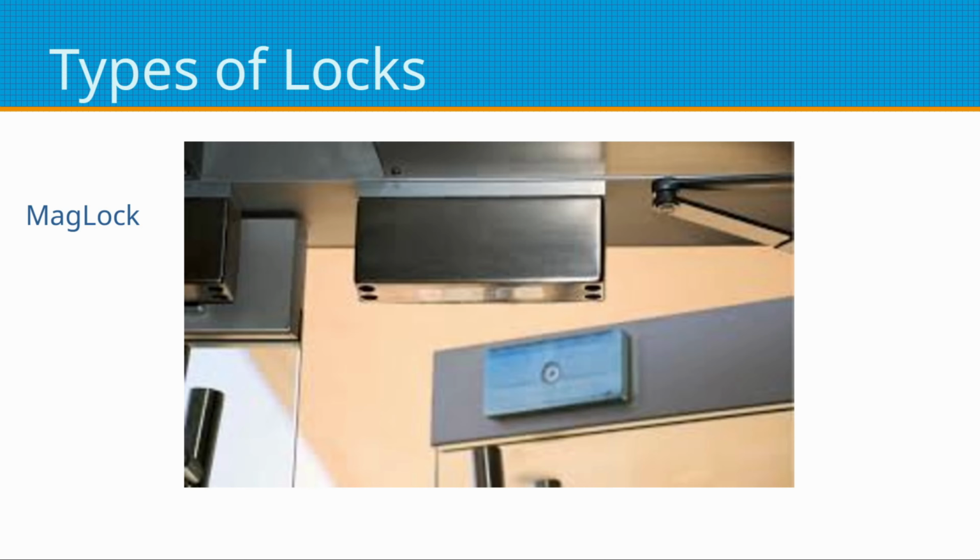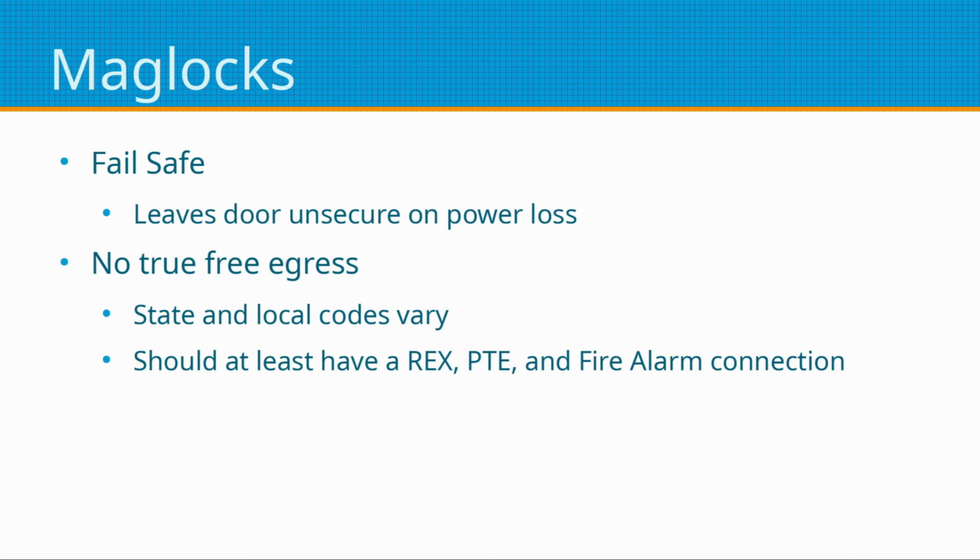They are very high security typically, but unlike the other locks where you can always get out, a mag lock you can only open if you drop power to it. And so if for some reason power will not drop to that mag lock, maybe the sensor was put in wrong, the release button was put in wrong, it's just got a failure, who knows, you will have people trapped inside. And that's why generally people don't use mag locks anymore, and there's actually some jurisdictions that won't allow you to install a new mag lock because of the life safety. And life safety will always trump security when it comes to consideration of hardware.